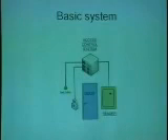Okay, so here's a basic access control system, like you'd expect to see. This reader could be a swipe, it could be prox, it could be a biometric reader, like fingerprint. Traditionally, in a basic system like this, you've got a single access controller, electric lock, and normally a push-to-exit button.